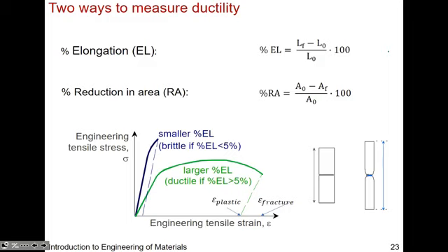So we covered this very briefly as well from the last lecture, where when we talk about a ductile material, we talk about, right, this plastic deformation. So this would not really occur for brittle materials, although we would just say your brittle material is not very ductile, right? When we talk about ductility, we talk about elongation of the sample as well as area reduction, or reduction of area. Sometimes it's AR, sometimes it's RA, but it's area reduction or elongation.